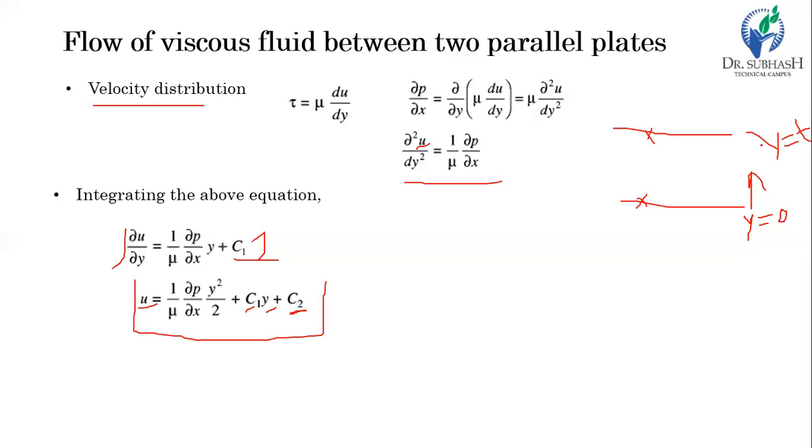So this is the value of y at the two boundaries. And when the viscous flow is in contact with any fixed surface, then the adjacent layer to the fixed surface always has a velocity equal to 0. So in this case, velocity equal to 0 here, and here also u equal to 0.